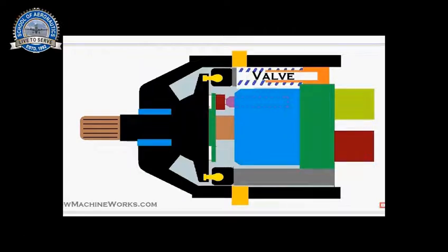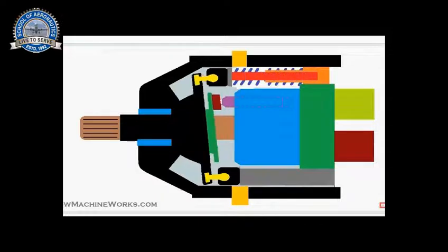So when the valve gets pressurized, the pressure is getting into the valve, resulting in the swash plate angle changing. So you can see when the swash plate angle changes, the piston is actually moving back. You can see that the movement of the piston back results in a suction. At the top the piston moves back, and at the bottom you can see the swash plate is moving towards the front. So that's the change in angle of the swash plate over there.